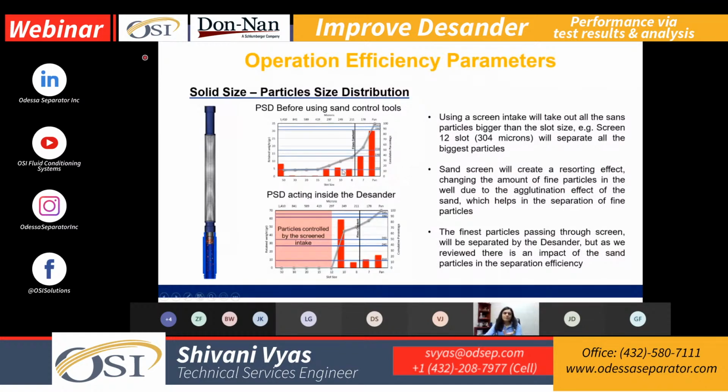In this particular case, we did a 2-stage filtration where we had a screen as the intake of the fluid, and then we have our downhole desander. Even though the size distribution shows a lot of finer particles, going back to what we just saw, the downhole condition and the particles agglomerating, we chose the 12 slot sand size to separate the first stage. Everything that's finer is going to get separated by the centrifugal force created by the helix and dumped into the tailpipe.